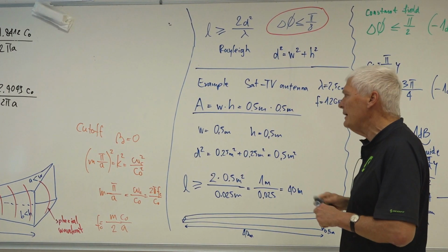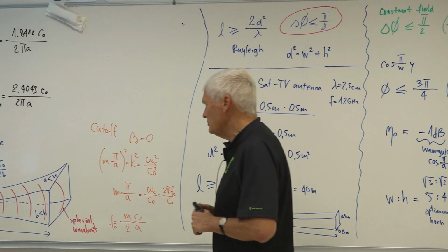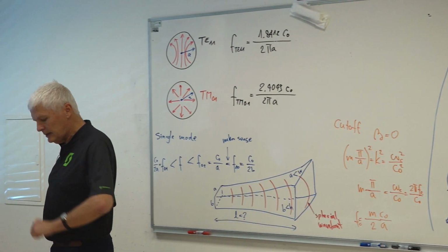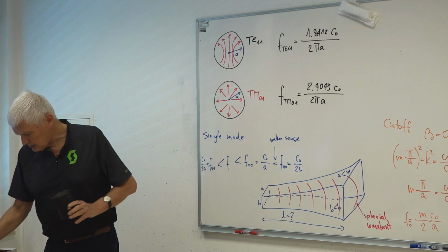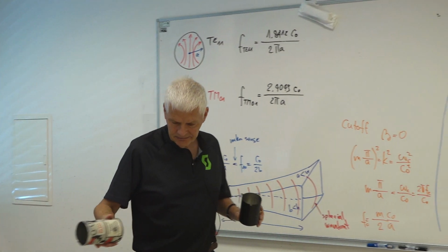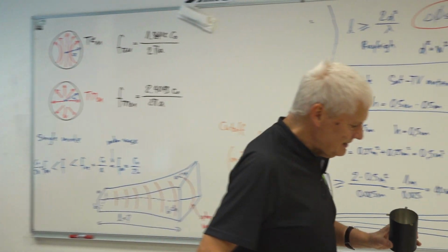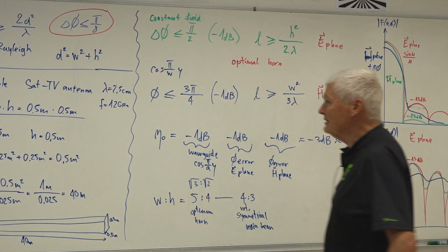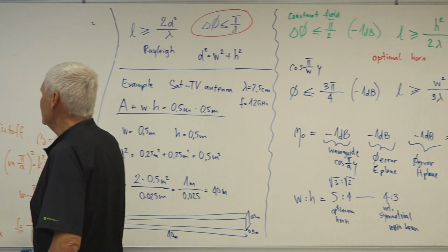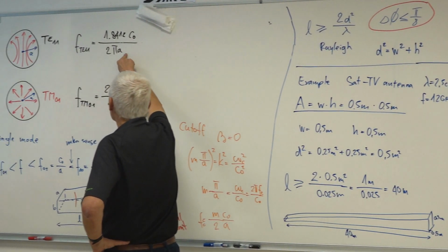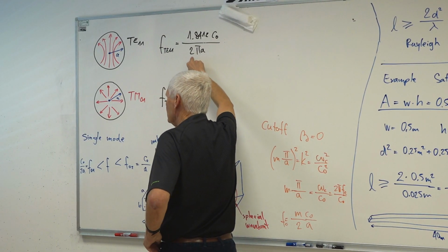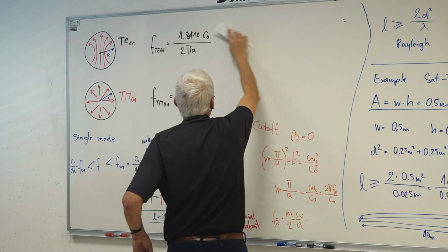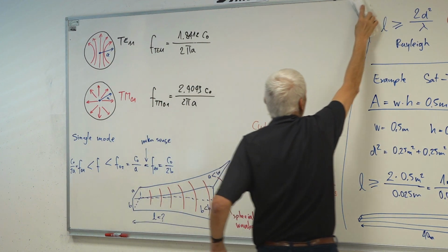Also here I have quite a restricted frequency range. So what you can do about this, you can build actually simple antennas, and these are two simple antennas built by students. The so-called coffee can antenna. You need a coffee can. What size? Approximately radius 5 centimeters. Times 2 pi, times 1.8, gives about 24 centimeters, you get the correct wavelength for Wi-Fi.